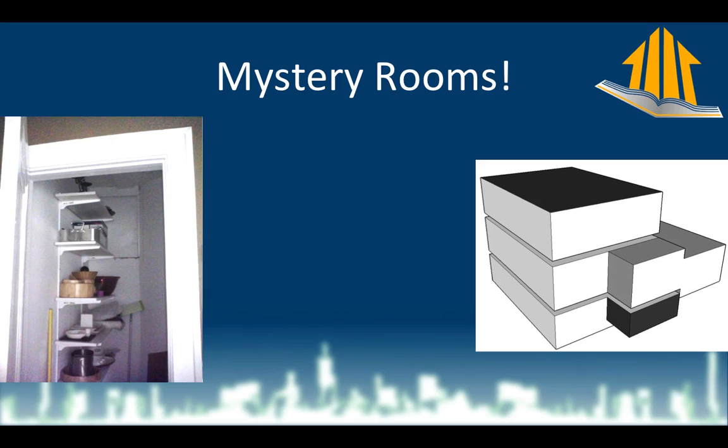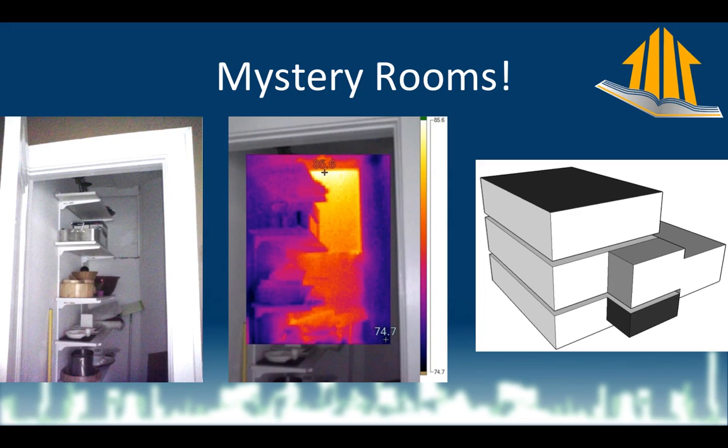And also, this closet is in the dead center of this house. So what should be going on behind there is nothing funny, no funny business. However, when we actually do run a diagnostic and I point my infrared camera at it, I can see that the outside air that's 85 degrees is somehow getting into the middle of my house. And that's not okay. So we're going to definitely want to know about all this stuff.